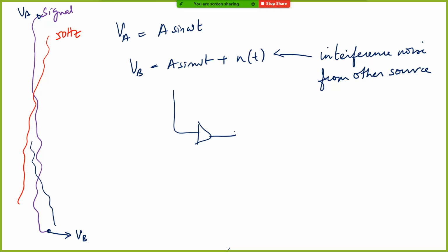So how to solve this problem? In fact, I think it was the BBC which came up with this technique, where they were running a lot of audio lines around their studio. So they said, why don't we run our signal itself as two lines, as a differential signal line.